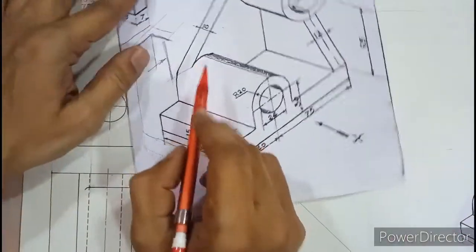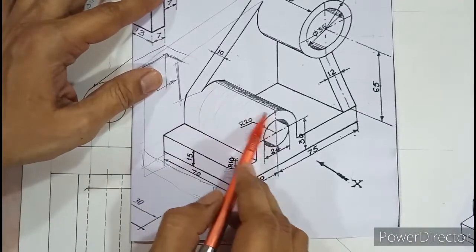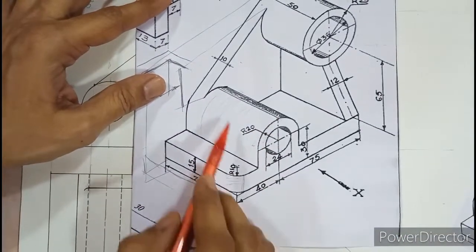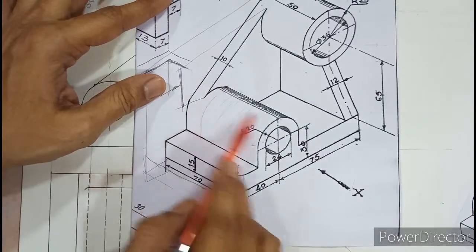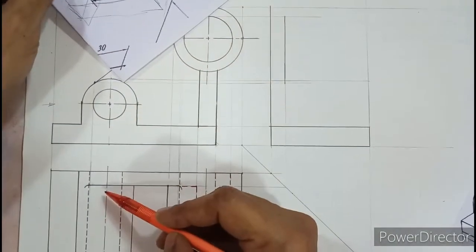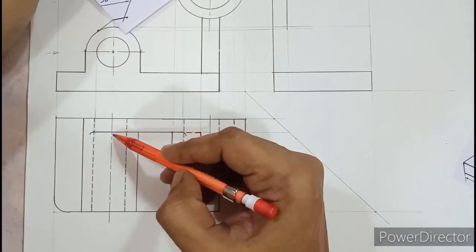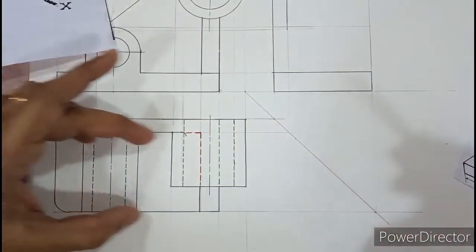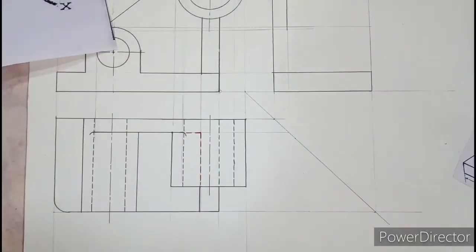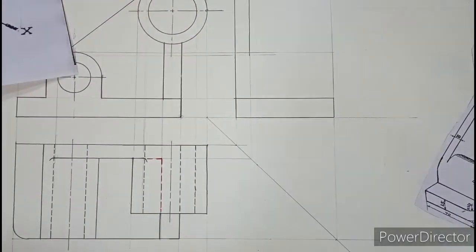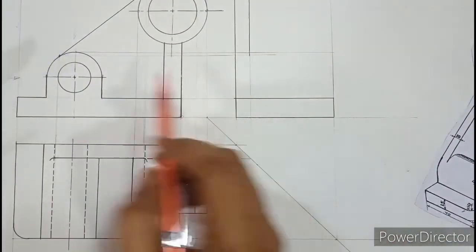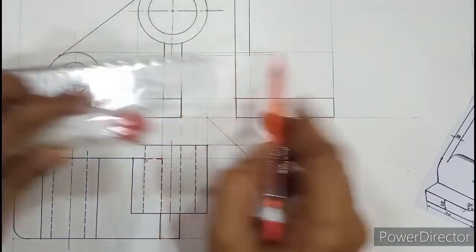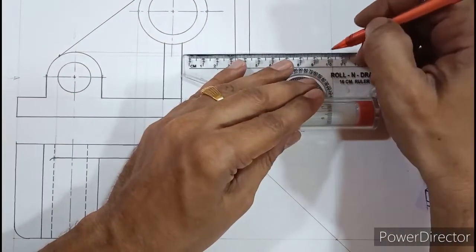Now what is the width of this? How much is the width of this? So it is 70 minus 10 behind. So this is 60 mm width, and that 60 in the top view is from here to here. Okay, this is 60. So that is already projected if you look here. So in the side view, what you should do is, the topmost boundary that is being projected needs to be darkened till here.